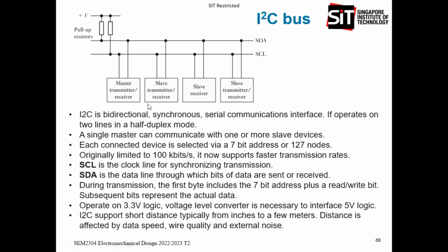Now, for the I2C bus, all the manufacturers already agreed beforehand. If I'm producing a display for the I2C, then all the displays will have a certain address, like 67 or another. Usually they will have 2 addresses reserved for each type of device. So I can have 2 displays.